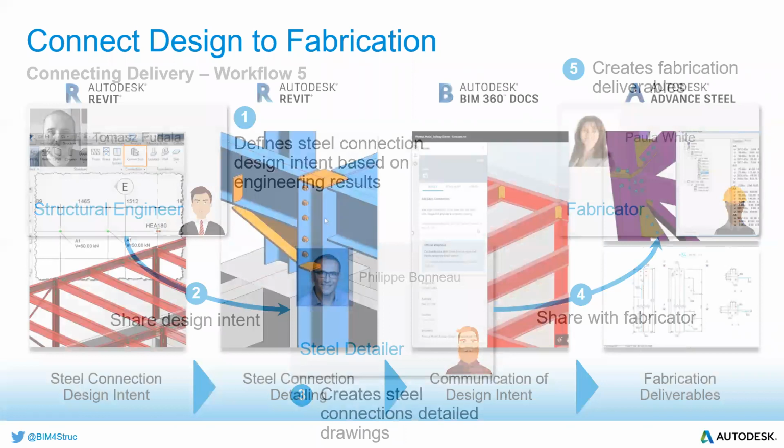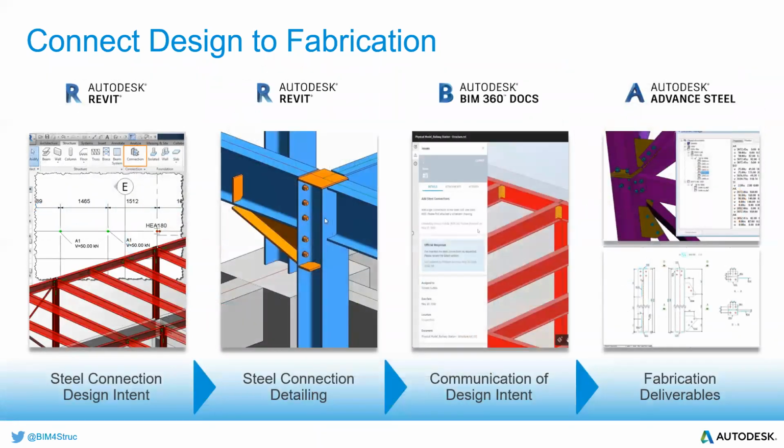So this still happens again in the same products that we had looked at previously, but mainly within Revit. So Revit has inbuilt tools for doing structural connections. So we know whether they're going to be the gusset plates, the holding down bolts, and what have you, all those are already present within Revit. So you're just supposed to specify them based on the kind of joint you're looking at. Then you will automatically be able to apply it to that specific connection that you want to design.